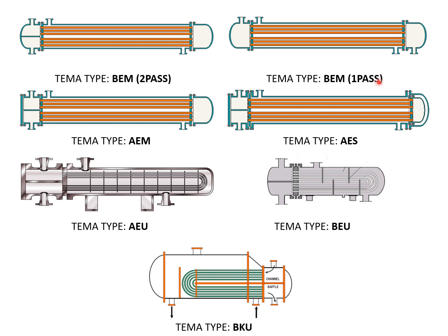The number of passes also increases the efficiency of the exchanger. If you want to increase the efficiency of your exchanger, normally what we do is increase the number of passes in the tube exchanger. In that case, we say that the efficiency of the heat exchanger is well maintained. So normally, instead of going for one pass, we always go for two pass, so that we have very good heat exchanging property between both the mediums in the shell and in the tube.